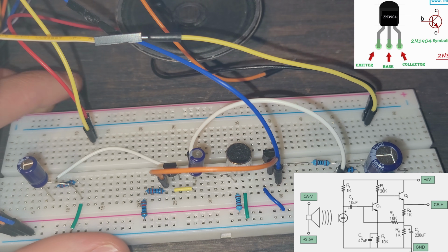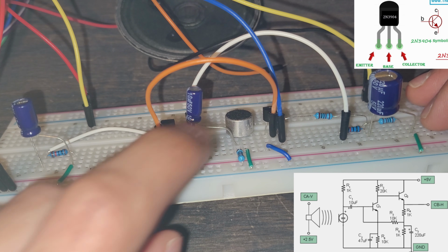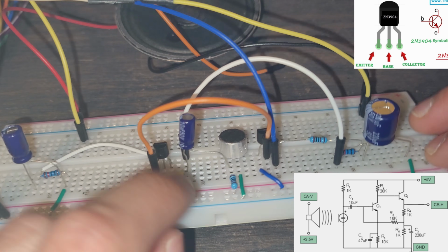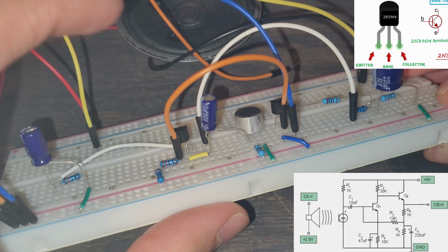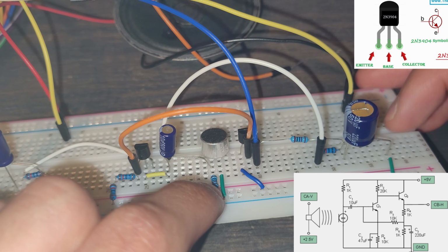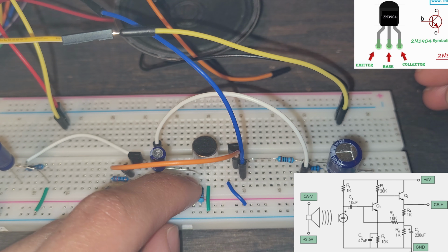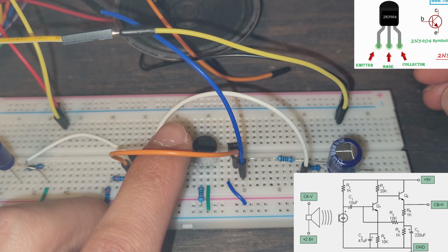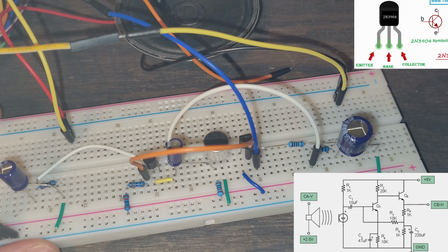Now we can see that we have a 10 microfarad capacitor with this. The positive side being the positive side of our microphone. So this is the positive side. The negative side is denoted with this little negative part right here. And we can see it is a 10 microfarads. It's in parallel with this resistor. So there's the node right here. We have a node right here, and it's going to split off. So that's going to be it for this part. We hit this capacitor. Now this capacitor is going to have 2 connections, but we're going to come back to that in a second.